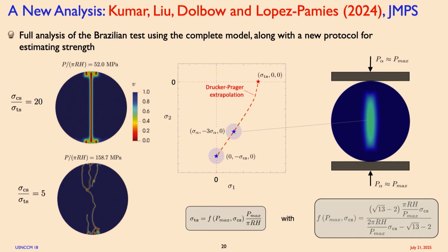It happens in a single step, and the mesh isn't perfectly symmetric. Now, we've also looked at ways to perturb the system by introducing spatial variations to the tensile strength, and that's another way where you can guarantee that as you refine the mesh, you converge on your quantities of interest. But in many of these problems, you find that you have to perturb something as a way to account for the stochastic aspects of strength.